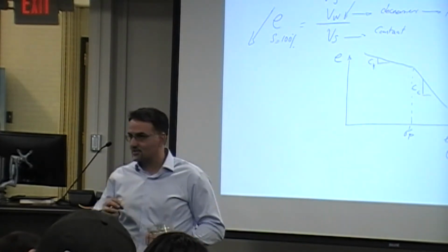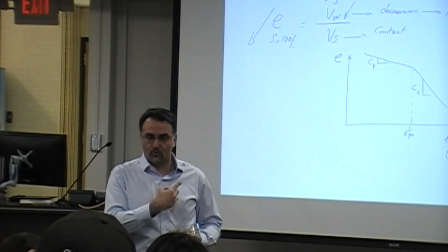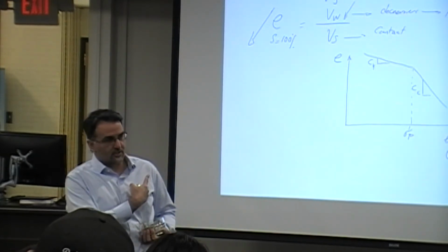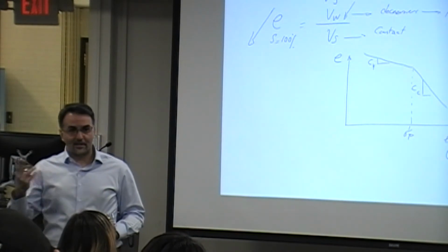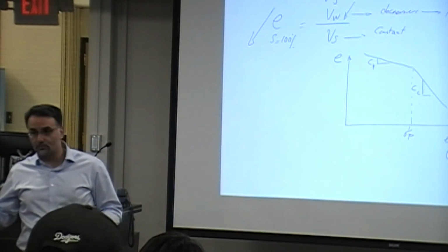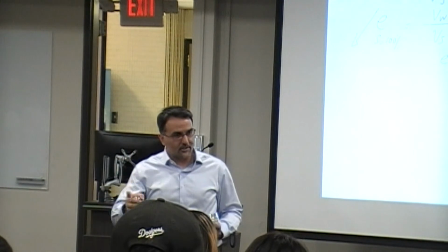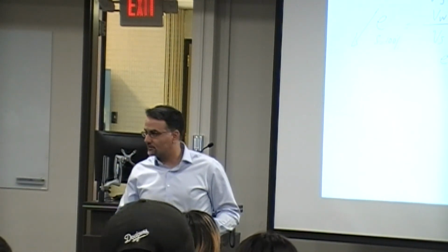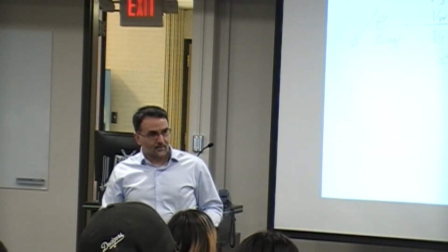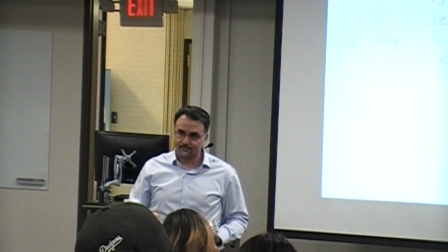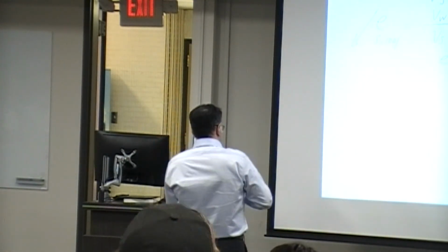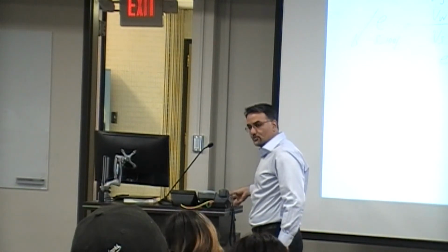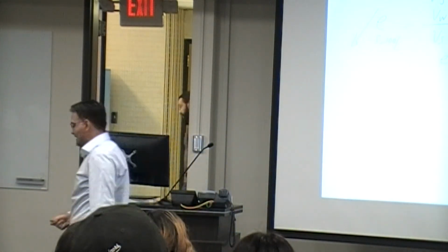The idea is to monitor or figure out 2 or 3 things based on that plot that you're going to generate. One would be the slope on the flatter side. The second one would be the slope on the sharper slope, right? And also you want to figure out what is the stress that the structure of the soil will break. We call that the pre-compression pressure, or the maximum stress that the soil has ever experienced throughout its formation. So that's basically the objective here, and then we use these 3 parameters to be able to do the calculations of the settlement.